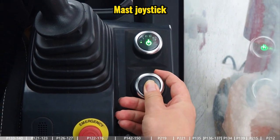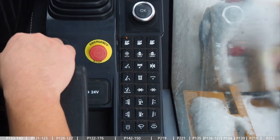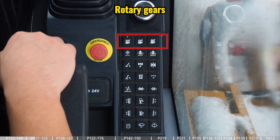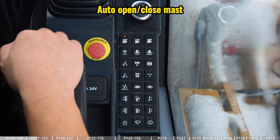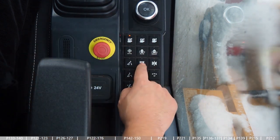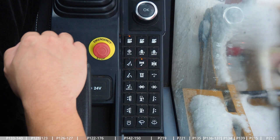We can use this joystick to adjust the mast manually. And for this big pad, the first line is for 3 different gears of the rotary, and the second line is for some automatic functions: the auto alignment of the mast, auto drilling, smart drilling. And then this button is for opening or closing the mast automatically, and this button is for the auxiliary winch unlock, because the first time we start the engine, if we want to switch between the main winch or the auxiliary winch, we need to unlock the auxiliary winch first by this button.